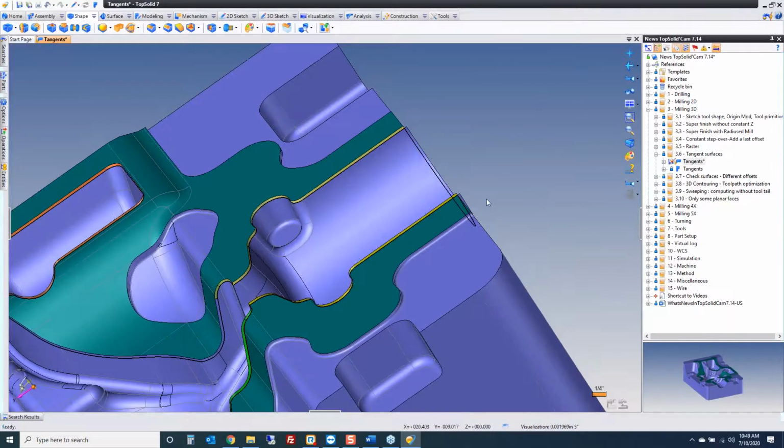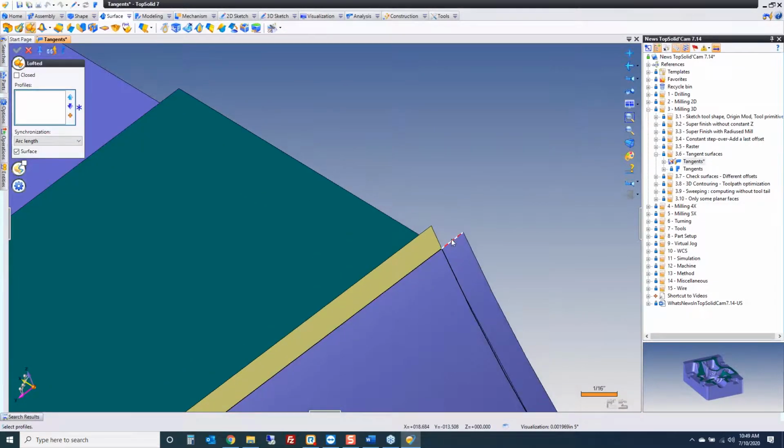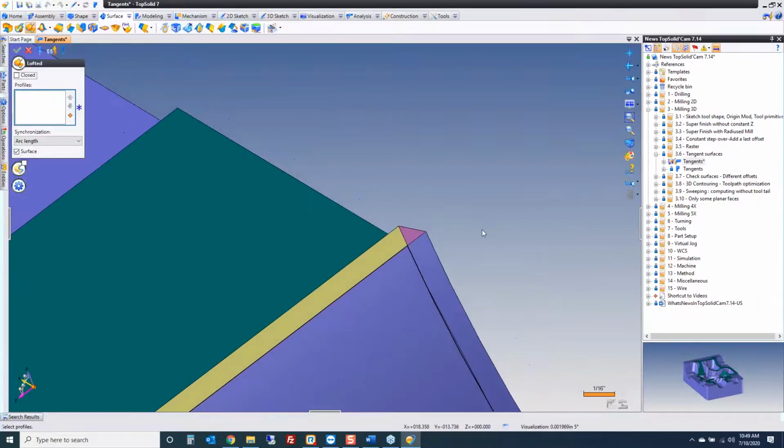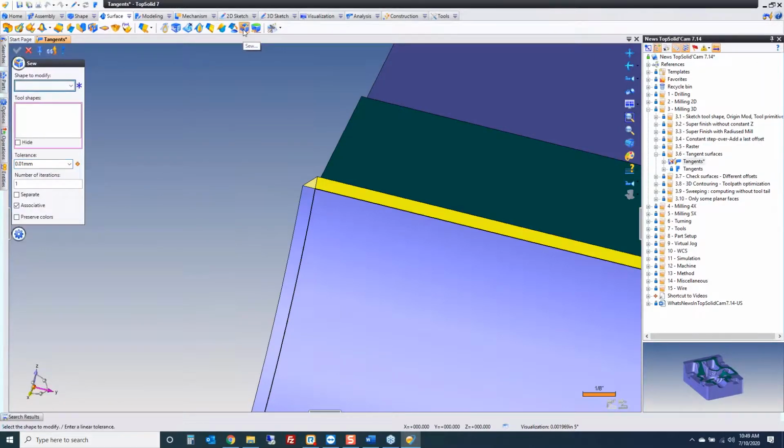Now, before we go on to creating the toolpath, I want to fill in the gaps there. So I'm just going to make a little lofted shape there. Again, here, I don't think it needs to be perfect. It just needs to have a surface. Do the same thing over there. And now, honestly, you don't need to do this, but I'm doing this to make the selection of the shapes simpler when we get to machining.